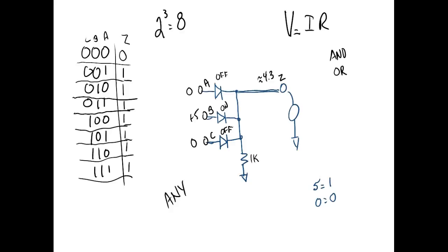So these guys don't do away with relays, but they take the place of the logic, right? And that's what a PLC does. A PLC does not do away with relays. What it does is the logic, the part that doesn't require a lot of current. And then when you need a lot of current, you use the PLC to pick up a relay and let the relay give it the current, which is exactly what your car does.